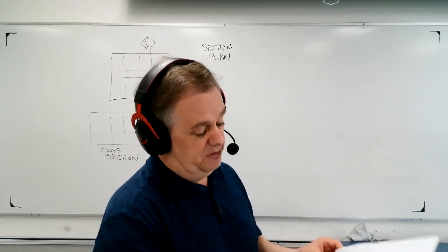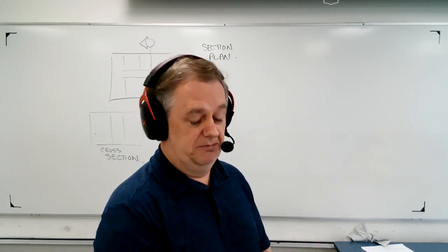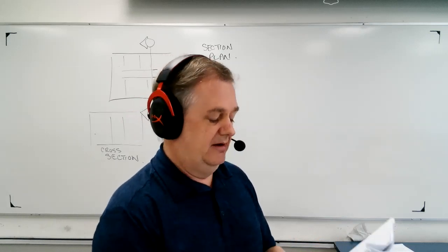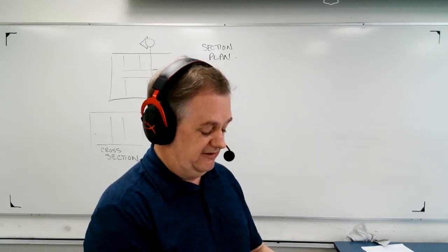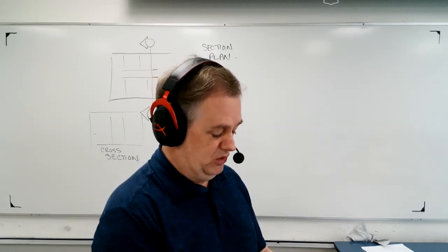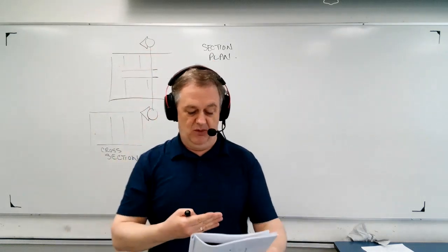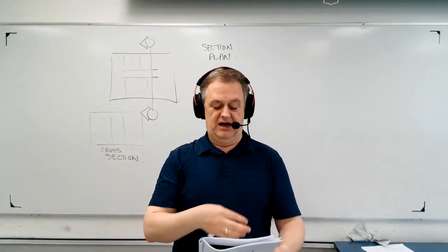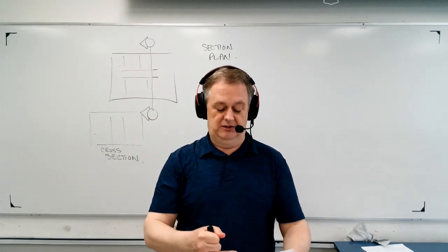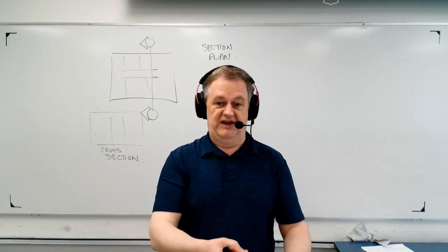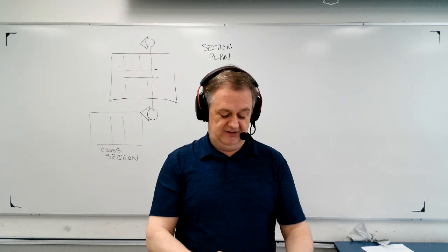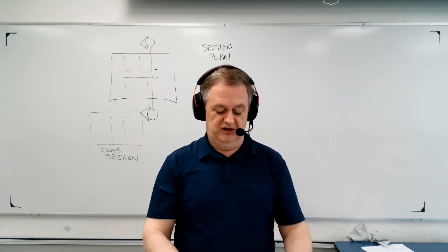And so if you flip the page over to page 10 and take a close look, this is literally view AA. Now you're looking at the cutaway view of that wall. You can see the roof line coming down. You can see how the blocks are done. Then there's facing brick on the outside. You can see the concrete footing. All the dimensions are given.